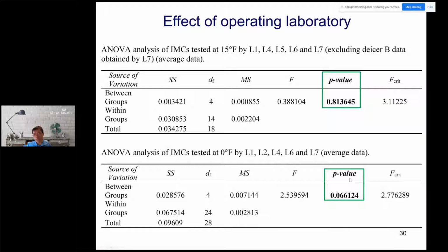There are 2 possible reasons. One is that at a cold temperature, the amount of ice melted is less. Therefore, the variation is higher in terms of measurement error. But the other thing is that when your thermals are at a much colder temperature, they're more sensitive to disruption from the ambient temperature when you're operating in that process.